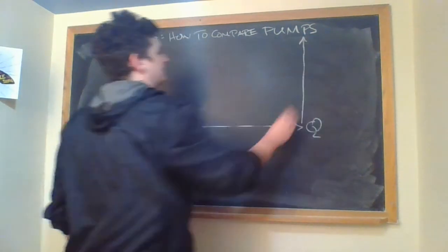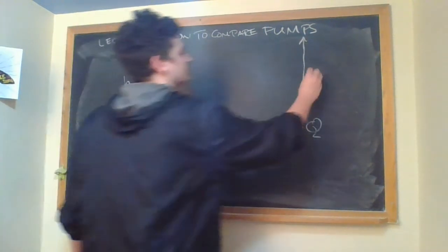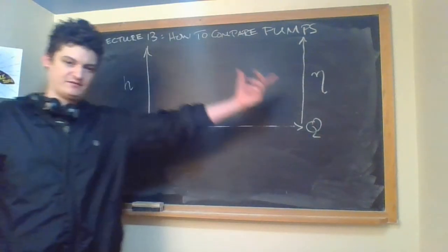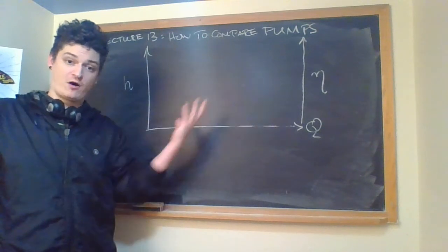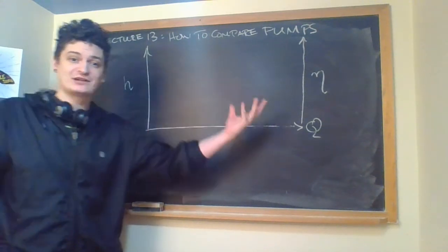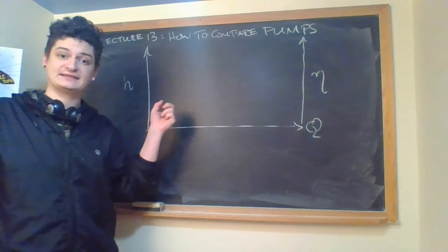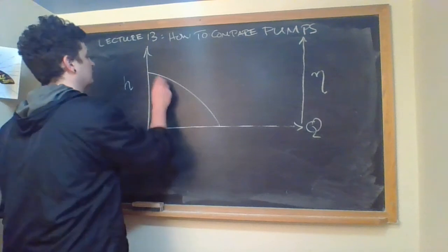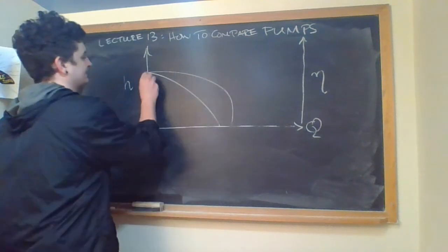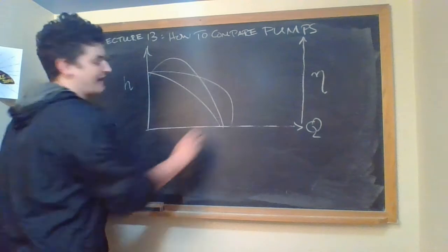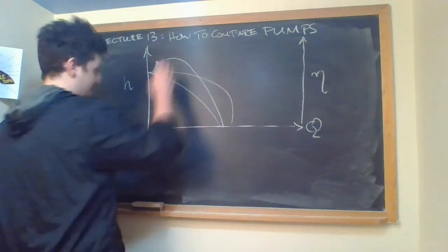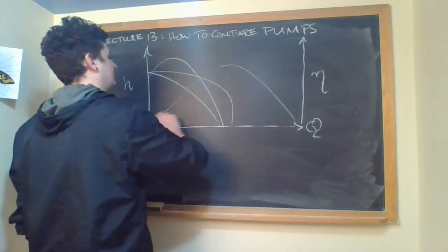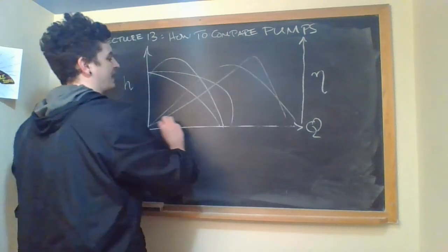Recall on this side, the other thing is you had a separate y-axis you compared to, and that was the efficiency of the pump. So these are things I definitely want to predict and compare. Different pumps are categorized based on these y-axes. Every pump has its own characteristic curve. So one would look like this, another could maybe look like this, maybe one could even look like that, etc. Same with these. Each one of these pumps has their own efficiency plot that maybe looks something like this.